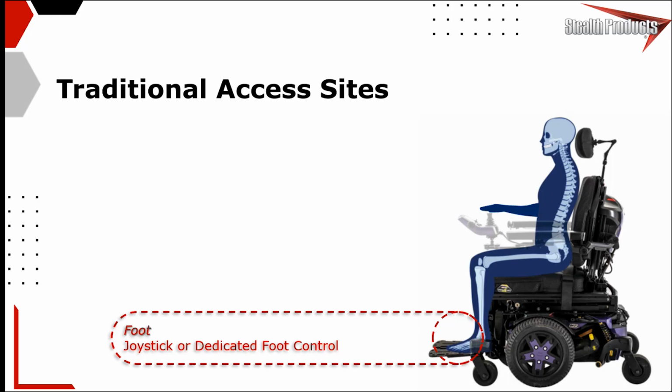So clients who have issues with function in, say, the upper extremities, chin, head, but maybe who still have relatively good foot control could benefit from a foot operated drive control. So there's drive control options that let you drive with knee extension or flexion for forward and reverse. You have the option for forward and reverse by, say, dorsiflexion and plantar flexion of the foot. And so that's going to change how it mounts a little bit.